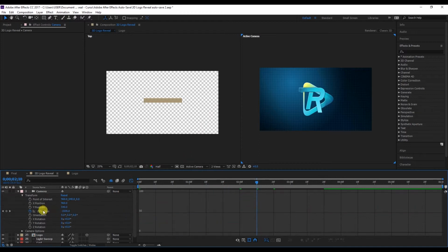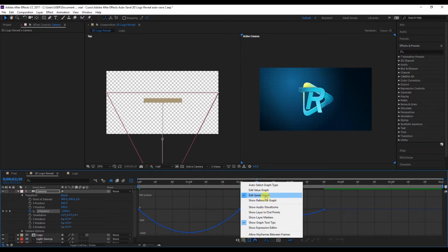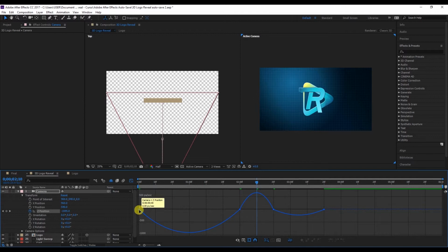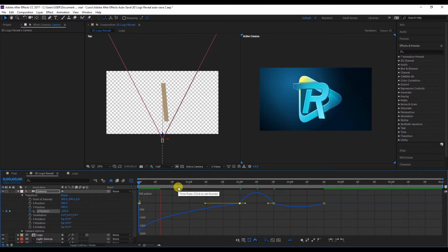We're going to click on our Z rotation so that we can see the curves. We're editing the speed on the graph. In the first point, we're going to modify the anchor so that it starts quickly. So we'll put it here. We can see that now it's going to start from minus 800 pixels per second. We're going to modify this anchor more or less to here. And that way we start from 1600 pixels per second. Let's hit play. And we can see there, it starts faster.